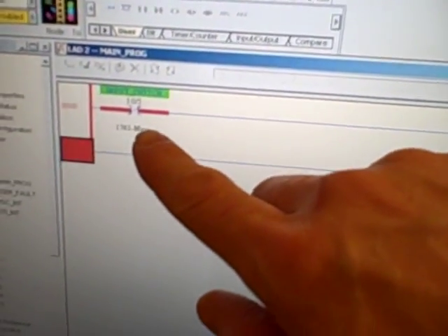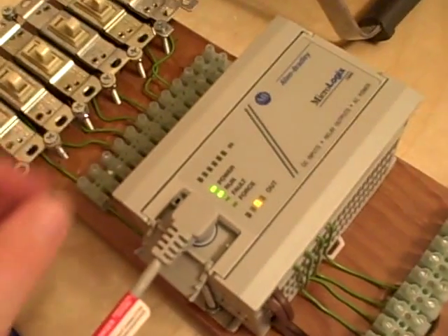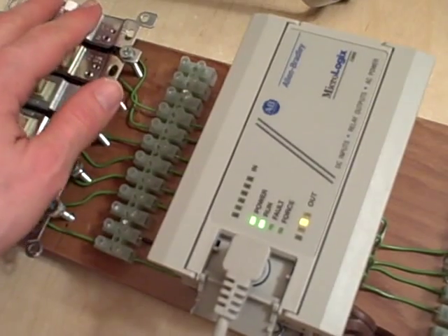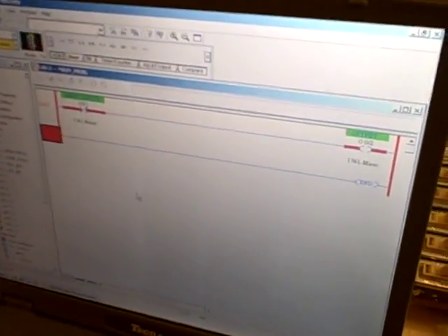When the input bit is off, its corresponding virtual contact is passing imaginary power onto the virtual coil, energizing the output. So I have an opposite or inverse correspondence between input bit 5 and output bit 2. And that shows a basic concept of coil and contact programming and ladder logic for a small PLC.